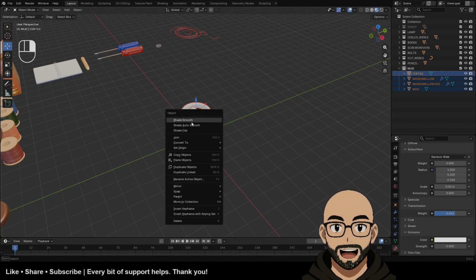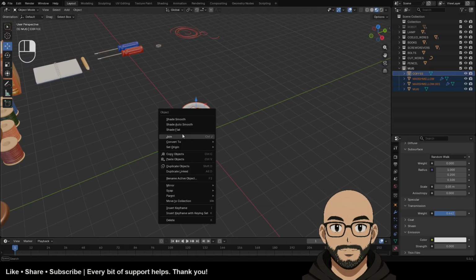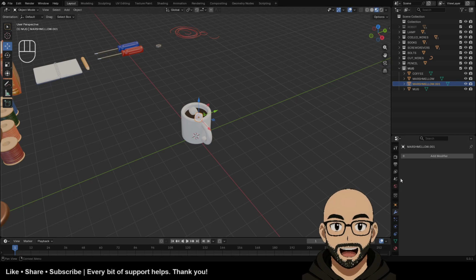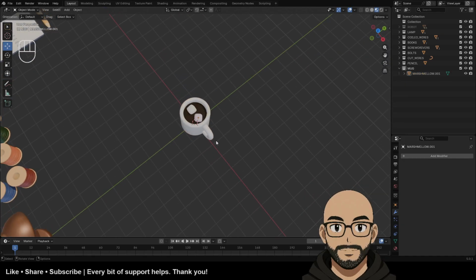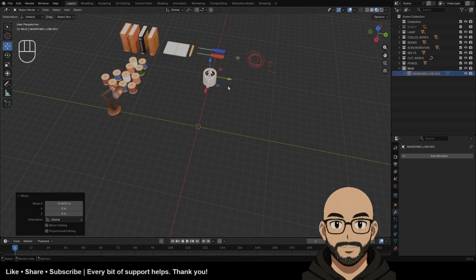We can group this all together if you want. If you don't plan to animate any of this rattling or moving around, make sure you convert to mesh. Those modifiers are applied, as you can see, and now join. And now we have a mug we can just move around on our desk.